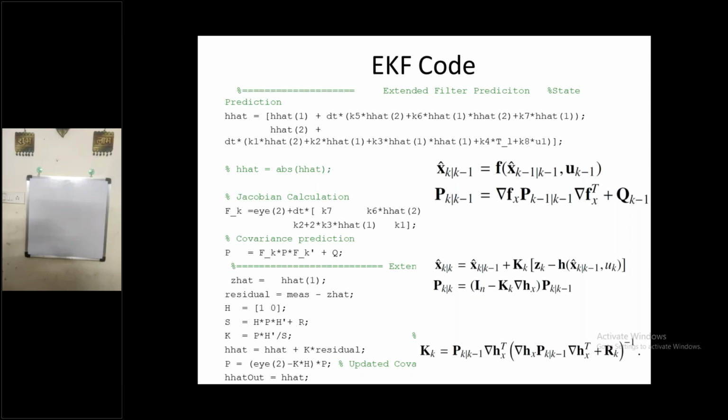So you can come up with a result which says that if the delay is 1 millisecond, then it will give a stable state estimate. That is called a time delayed extended Kalman filter or time delayed Kalman filter, which is also available in the control literature. In its very naive form, we assume that the sampling data from a particular sensor is 100 hertz in most cases. Minimum is 100 hertz; maximum it can go to very large values as well. In general 100 hertz works very fine. So that is my answer.